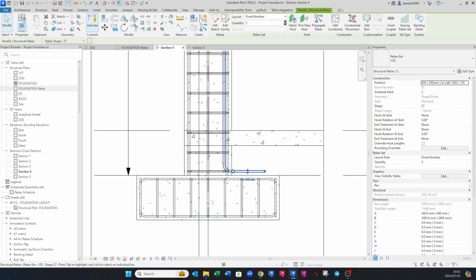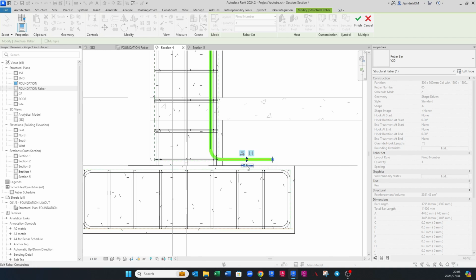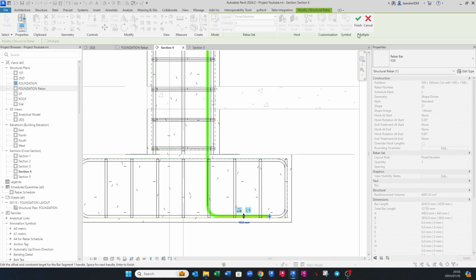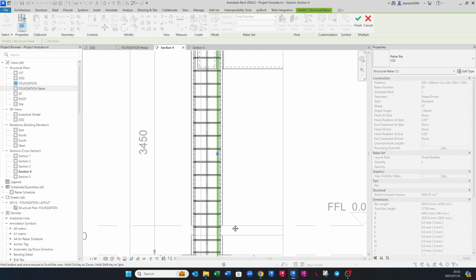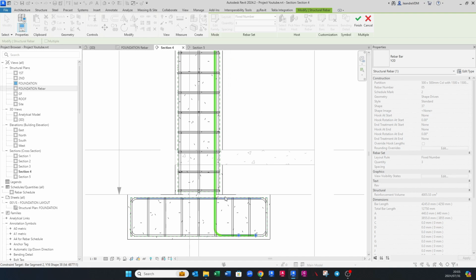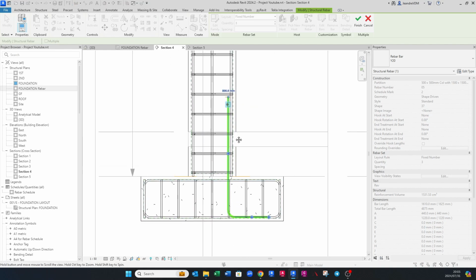So here we are. So now we can just edit the constraints. We're going to click where we want it to go to from middle. I'm going to make it 10 because the bar is 20, so that it just sits flush the underside. Then we want the top of this bar to come down to this level, but we want it at an offset of 800 for your splice length, like that.